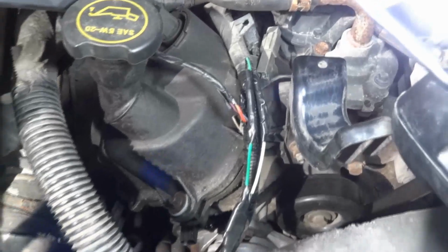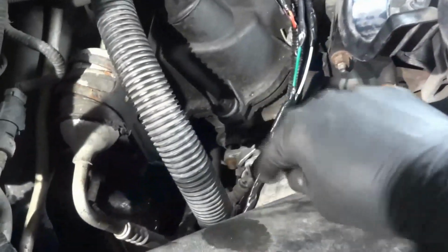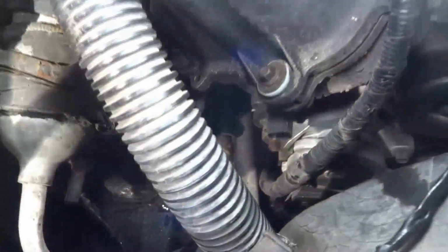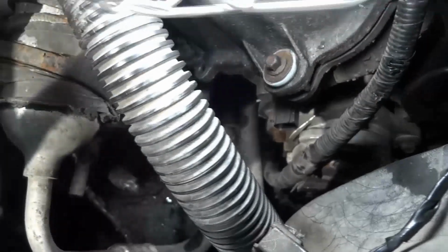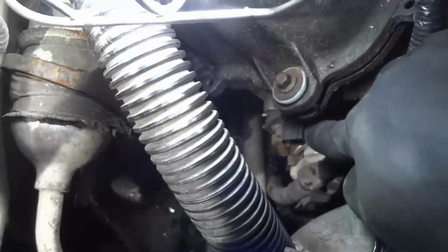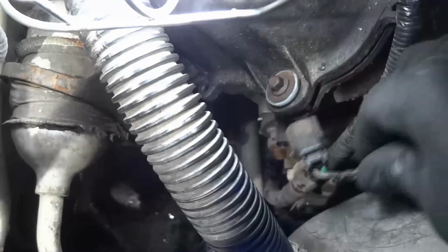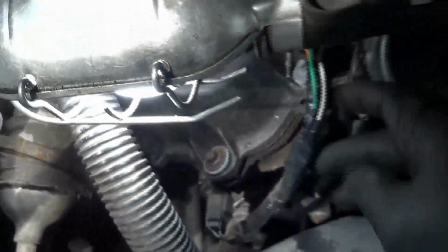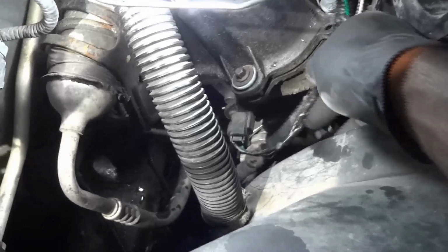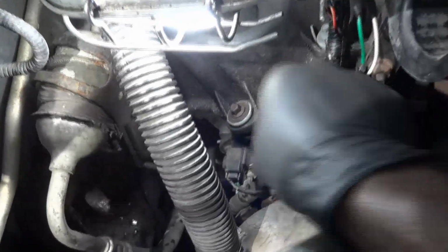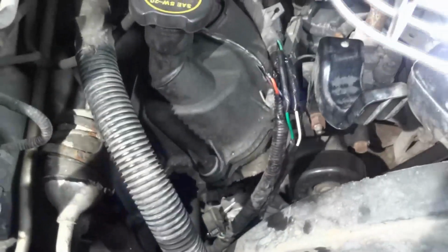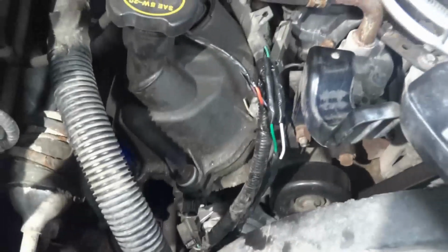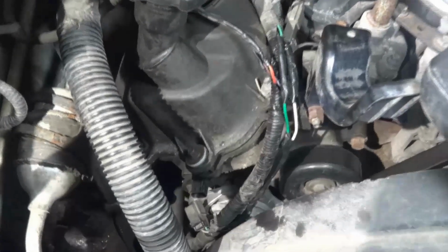Okay, so I reconnected everything, and here is the connector for the sensor. Okay, and this is gonna go right there on the sensor. Okay, so the sensor is right here. This is the camshaft sensor, so this connector will go over here. Okay, now we're gonna tape this up very well, and we're gonna tape it against this harness. Okay, so now I'm gonna tape up the wiring, and I'm gonna show you the wiring again after I have everything taped up, and then we will verify our repair. So now let's do that.